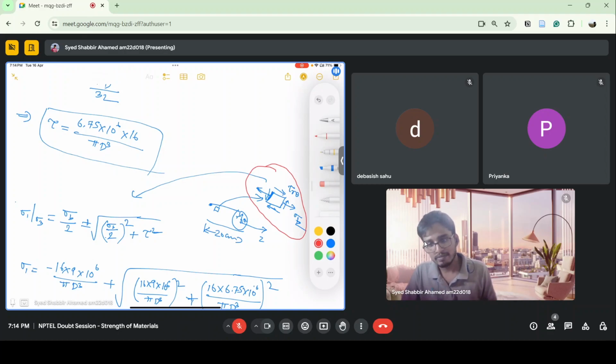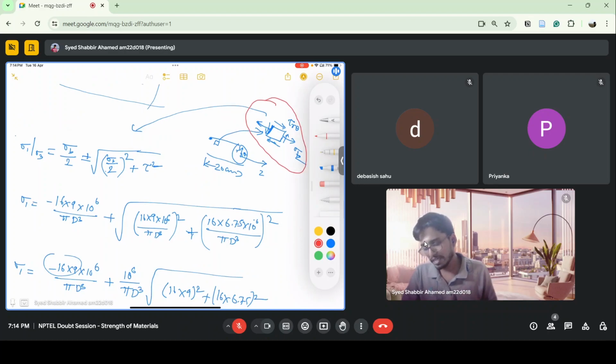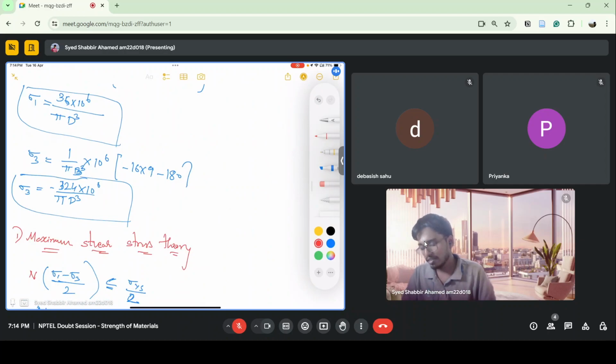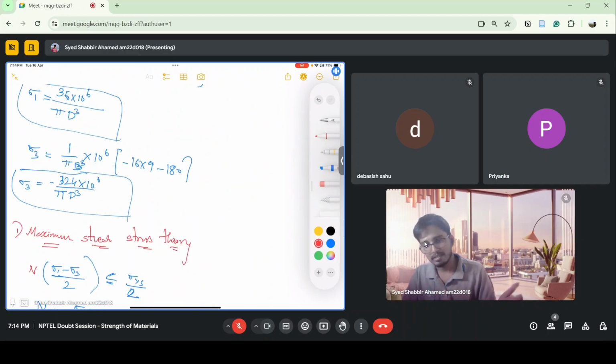And now we have to find out what are the maximum and minimum principal stresses. So we know sigma xx plus sigma y by 2 plus or minus root over, again, whatever. We have learned this in the Mohr's circle chapter. We use that, we determine the maximum principal stress in terms of d and the minimum principal stress in terms of d, and we don't know what d is.